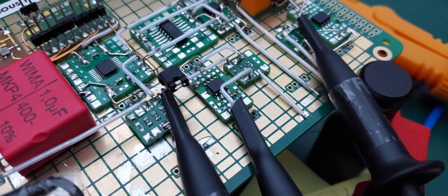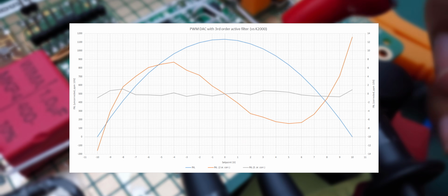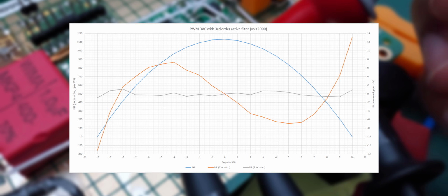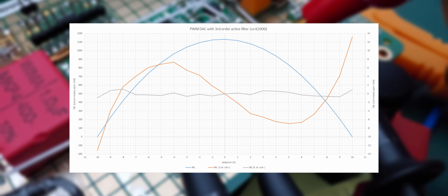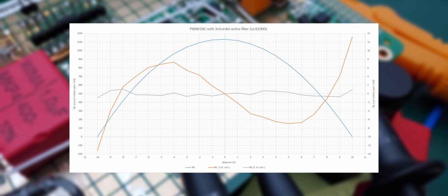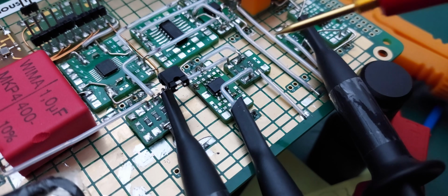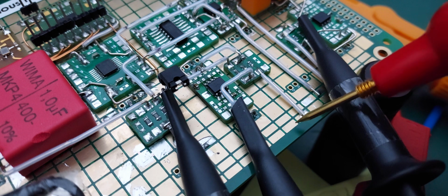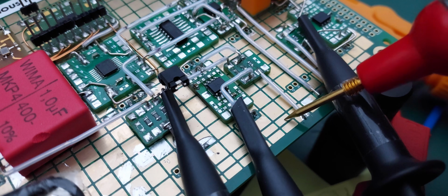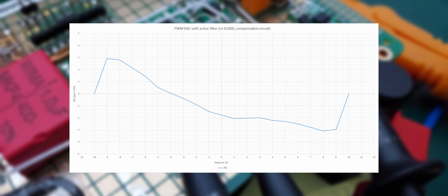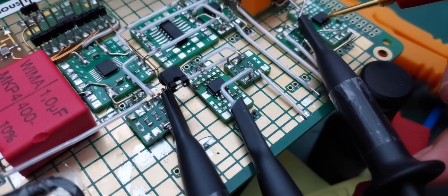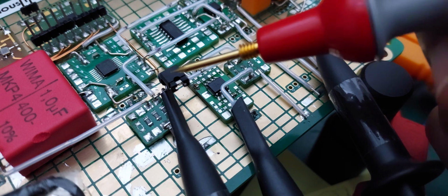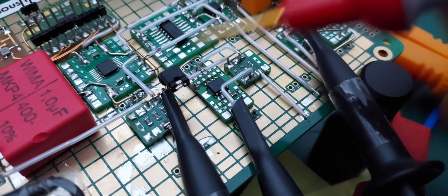This first attempt delivered predictable results. The INL was mostly quadratic, but just a second-order correction was apparently not enough. A third-order correction is needed to get the INL down below 1 ppm. With basic operation verified, it's time to try the compensation amplifier. Surprisingly enough, this time, it's not enough to fix the INL completely. It took me some poking around to find out that the pre-filter was the cause, so I'll have to trade